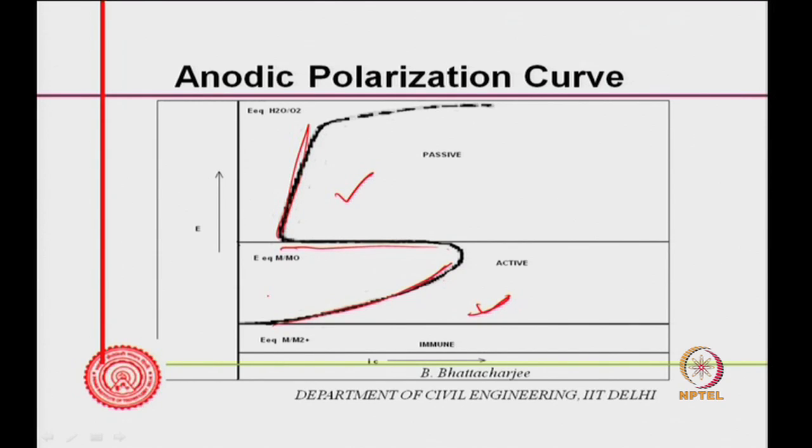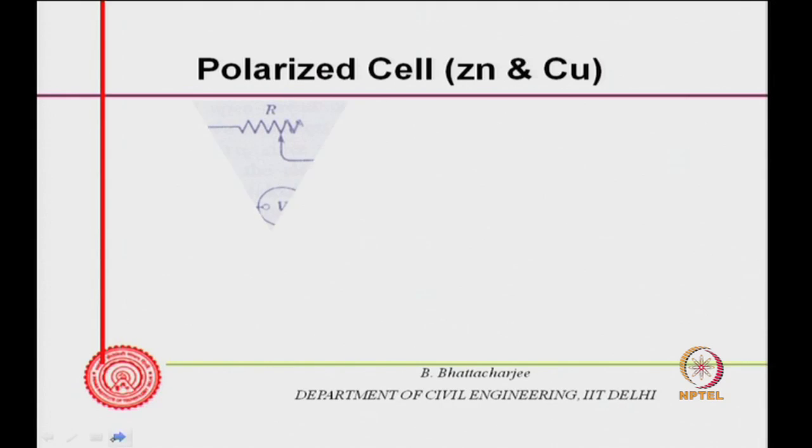Corrosion rate is measured in terms of current, because we talked of charge transfer, Fe ion dissolving. So, when current is less, corrosion rate is less. Suddenly the corrosion current has become less because an oxide layer has been formed, and then this is called the passive zone, this is called the transpassive zone, and so on and so forth. The immune zone is below this, et cetera. So, one can experimentally determine something similar to a Pourbaix diagram and verify this scenario for various concentration situations. So, experimentally determining zones of corrosion is also possible.